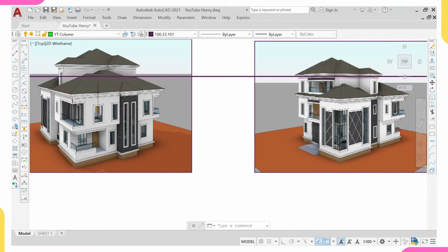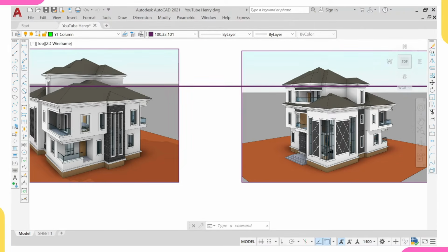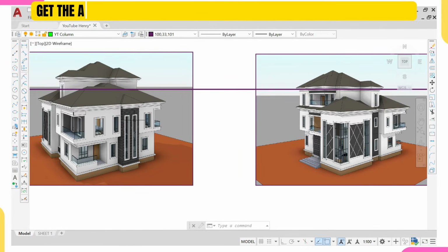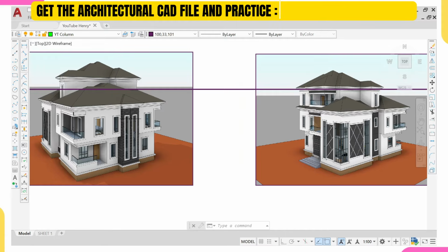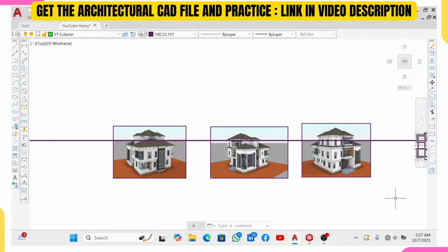But if there is something else, like steps, on top of it, please try not to insert a hidden beam; it is more advisable to insert a beam. But if you are a professional and you know what you are designing, yes, you can go with it. If you are still starting up, please don't rest it on top of a slab, unless the only thing that column is carrying is the roof load. In this case, our column is carrying just the roof load.